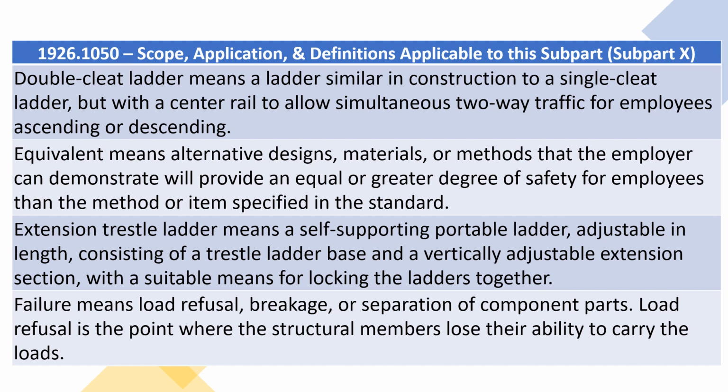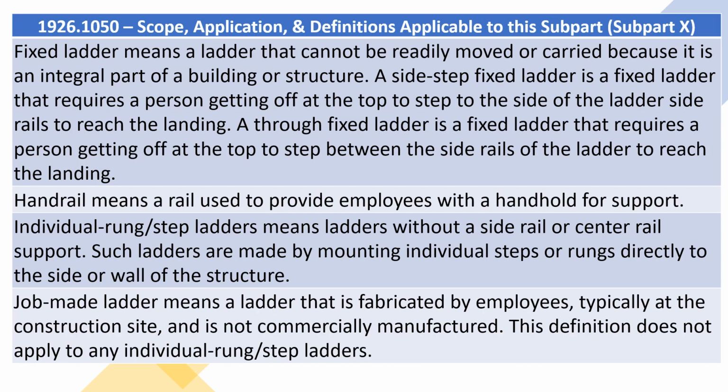Failure means load refusal, breakage, or separation of component parts. Load refusal is the point where the structural members lose their ability to carry the loads. Fixed ladder means a ladder that cannot be readily moved or carried because it is an integral part of a building or structure. A sidestep fixed ladder is a fixed ladder that requires a person getting off at the top to step to the side of the ladder side rails to reach the landing.